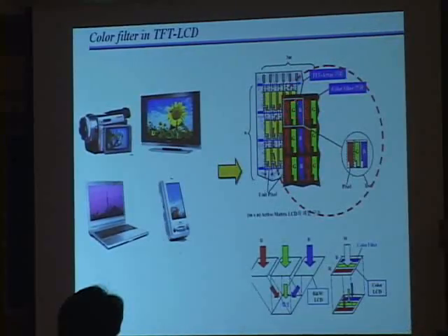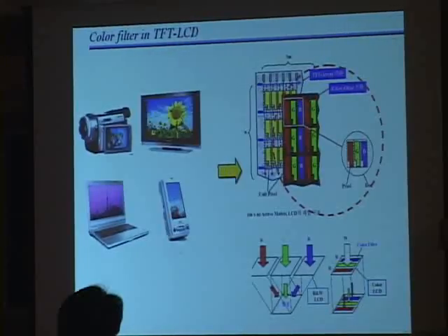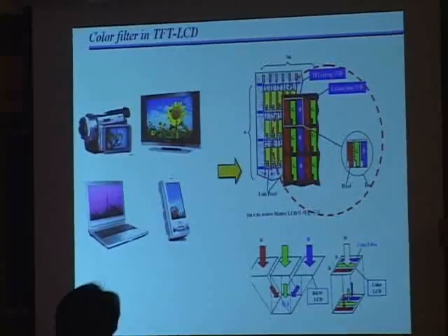Well, there are basically 2 materials for black matrix. One is metal, such as chromium, or the other is polymer resin. So because polymer is intrinsically transparent, for thin film, we need to add some black carbon black particles to obtain a high optical density.